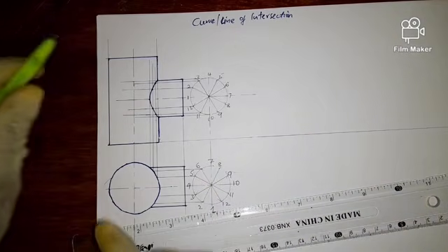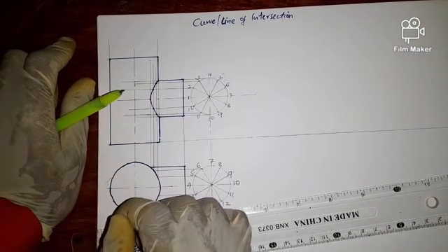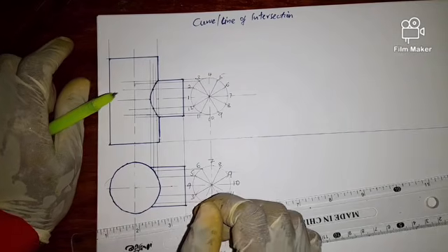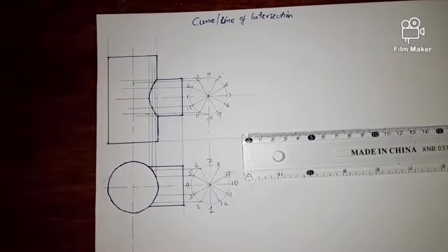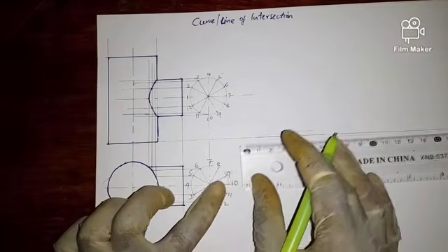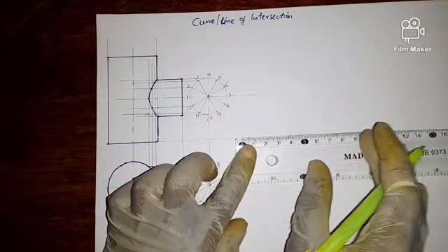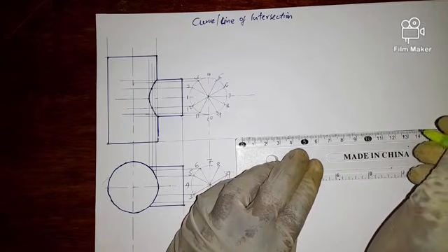So what we shall do first of all is to get the circumference by taking pi d, that's 22/7, multiplied by diameter, which is 40, and see how far it will go. So after calculation, you realize that the circumference is 125.68 millimeters. So we are going to measure 125.68 along this base. We can start it here. Then we measure 1 to 5. That is 12.5.